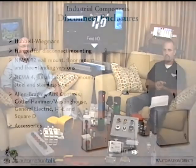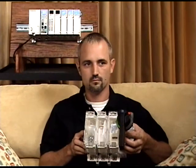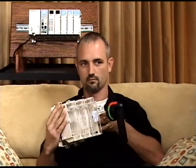So let's continue with the disconnect enclosures. In my experience as an electrical designer, a lot of times after you've designed a control enclosure and you've selected and laid out your panel layout and your size, you're going to have some kind of circuit breaker or disconnect or fuse disconnect to kill power to that panel. Yep, that's a fused disconnect switch.